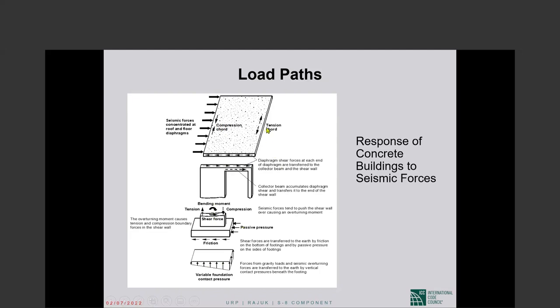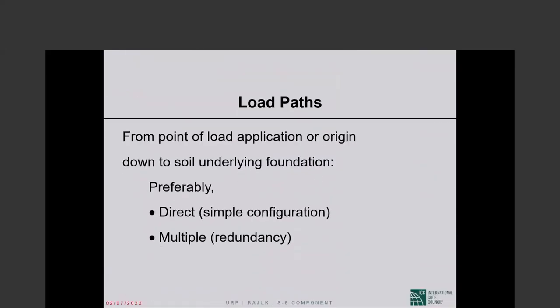Okay, so this picture tells you the concept of the load path. In this case, the inertia forces are going through the diaphragm to the vertical elements of the seismic force resisting system, as we call them, the columns and the shear walls, which take them down to their foundations, and the foundations transfer them to the ground underneath the building. So, a very important concept: load path, from the point of load application or origin down to the soil underlying the foundation.